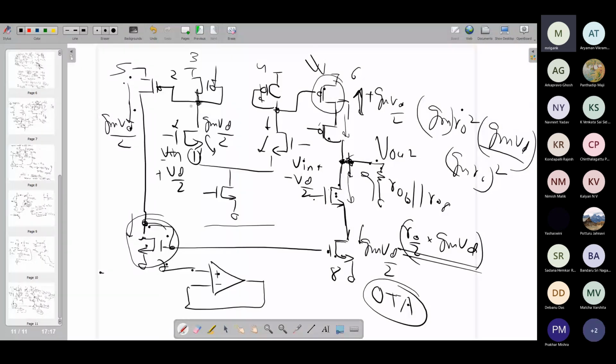As we discussed yesterday, we have small signal currents produced at the two outputs of the first stage, depending upon the input signals applied, and that reflects in the output stage. The small signal current in M4 is directly mirrored into M6, and the small signal current in M3 gets mirrored into M5, then it goes to M7, then M7 to M8 mirroring, and therefore it comes out of M8, and then the M4 to M6 mirroring.